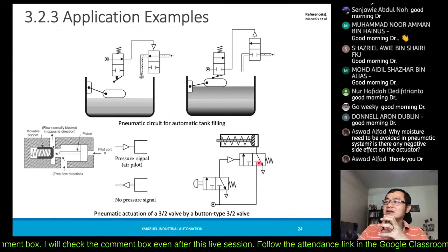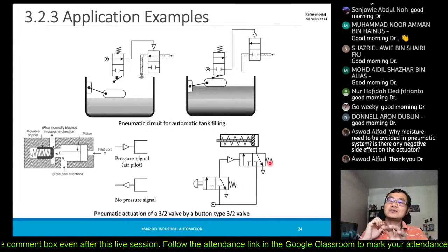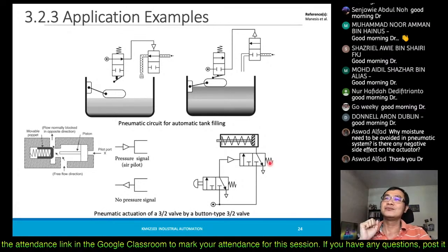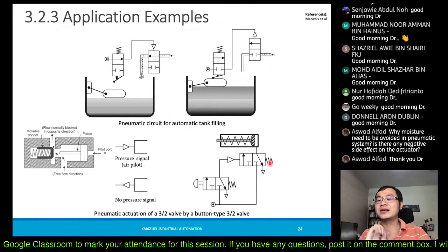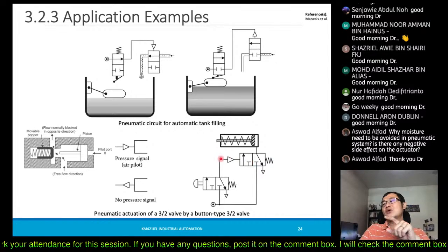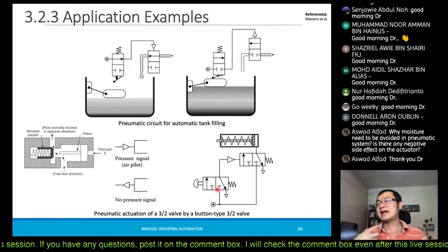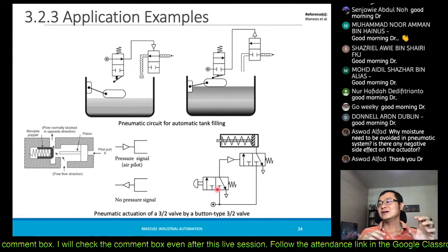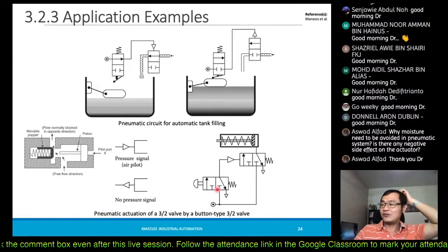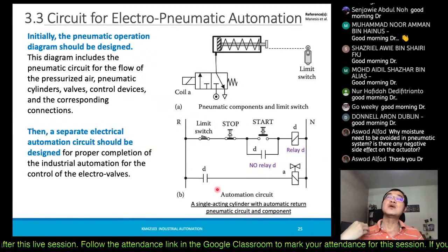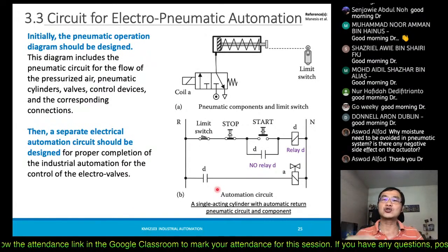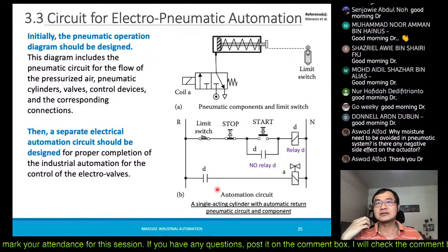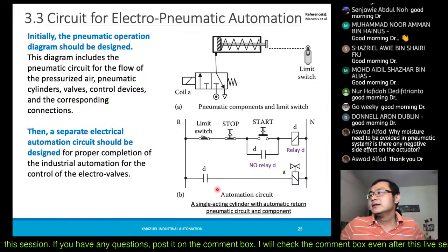That's why this may be too large and not practical for you to operate manually by hand, so you may want to operate it remotely through another valve. This is the idea behind using one valve to activate a second valve. This is a way of using fluid power to control, instead of a purely electrical control signal.